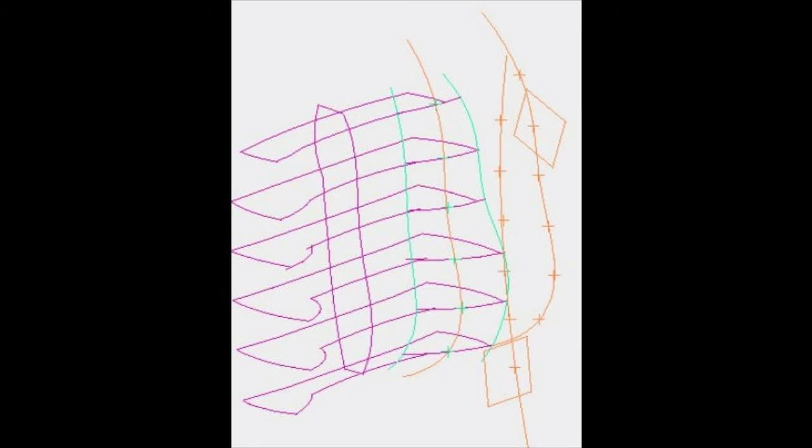Now the curves can be created using the same technique used when creating the limit curves. Once these two curves are created, they need to be combined back on the construction geometry. The curves should be projected along the normal lines of the plane that they were created on. See the image on the screen: the points and the curves on the projection plane, as well as the final curve on the geometry. The projection direction is normal to the plane where the curves were created. Now the surface can be created.